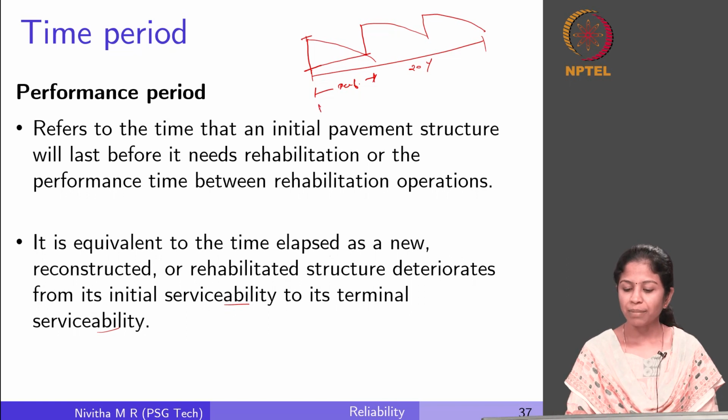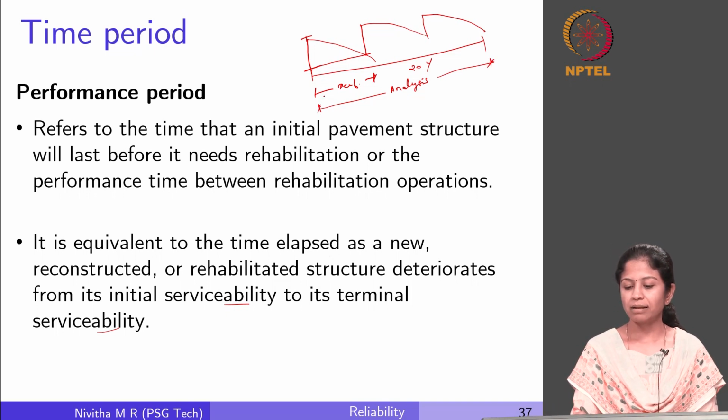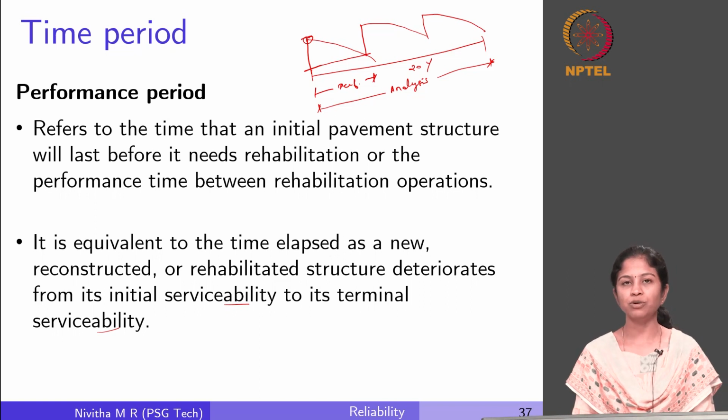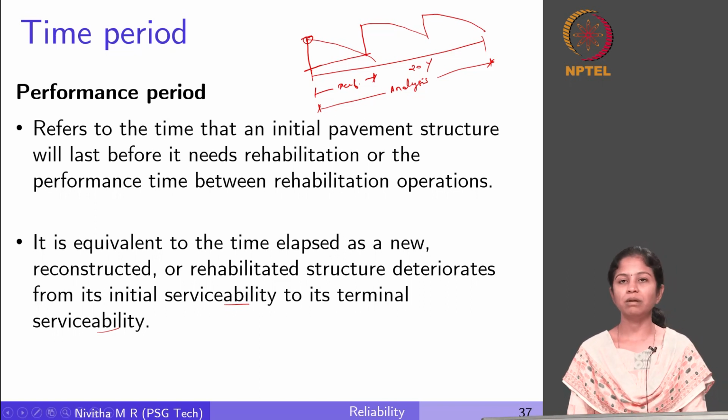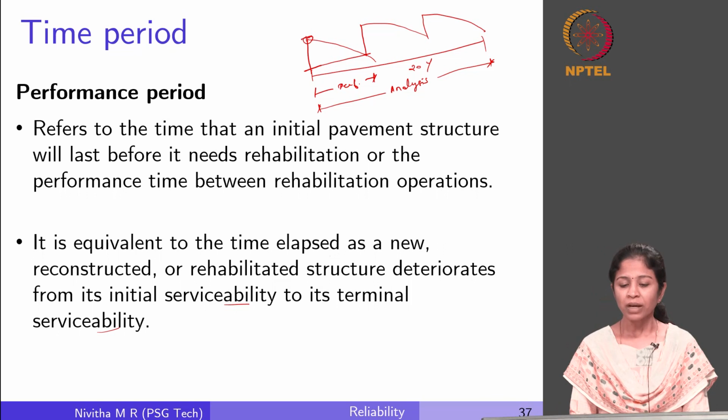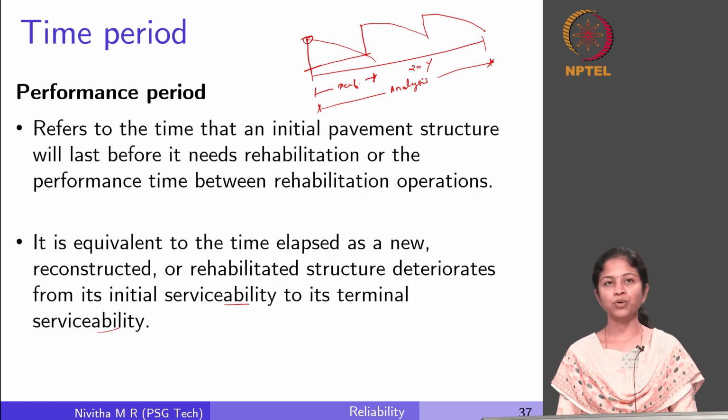So this is my analysis period over which I am interested in monitoring the pavement, and this is the performance period. One single treatment, how much time it takes to reach the minimum serviceability level. So this is the difference between these two terminologies.